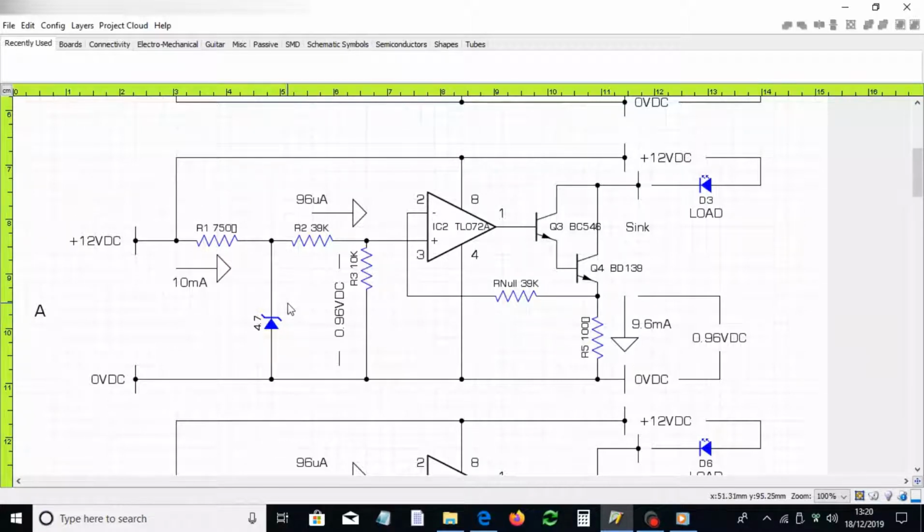Maybe out of 1,000 Zener diodes you can get a couple of them that perform very well. You can also compensate for the percentage drift per degree C by including a conventional diode in series here with the equal and opposite percentage shift per degree C as a Zener diode, so therefore you maintain stability on your reference voltage that way.